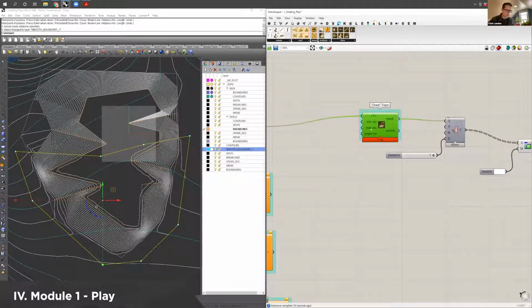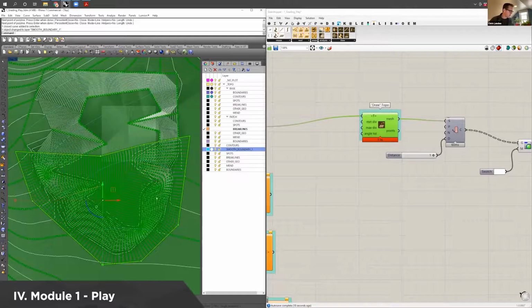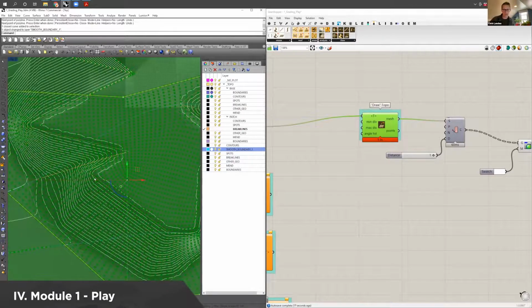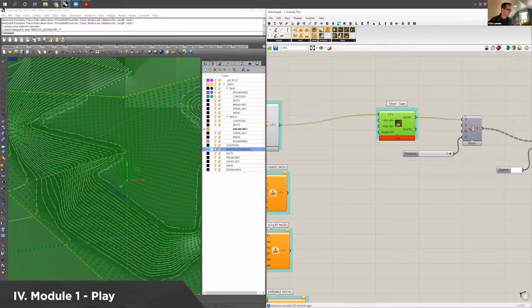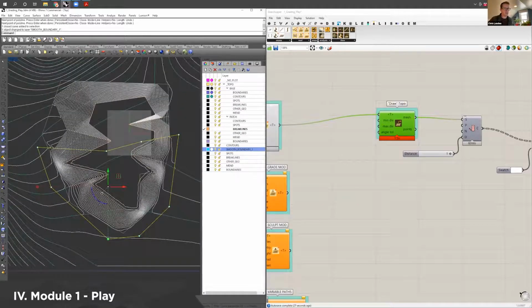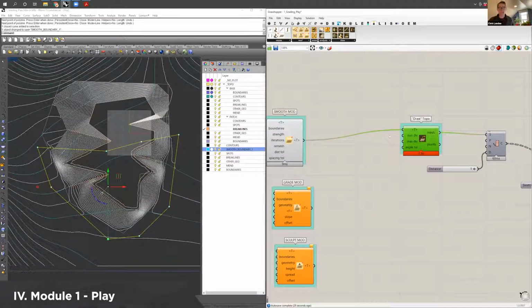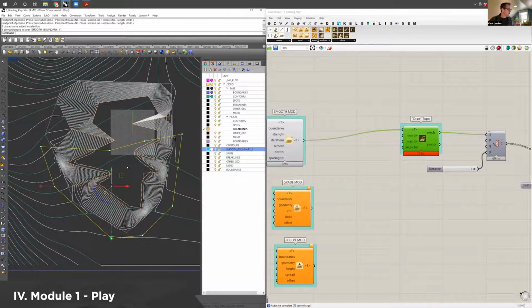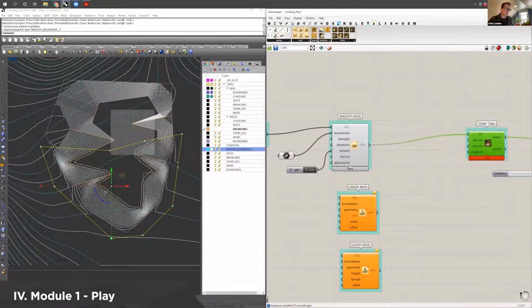But if I preview the draw topo again, you'll see that they have a crazy pattern to them, and that's like the quad remeshing that it's doing in that area. So that's pretty fun. It's taking advantage of some of the latest stuff. And if you're working in Rhino 6, remesh just won't work. The remesh part of it won't work. But you can change the spacing as well. So instead of 4 feet, I could do 10 feet.